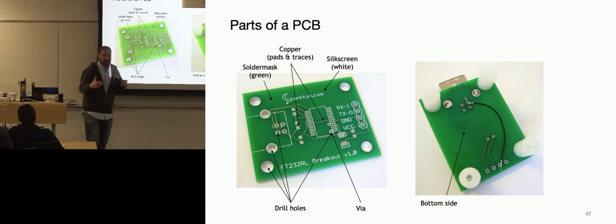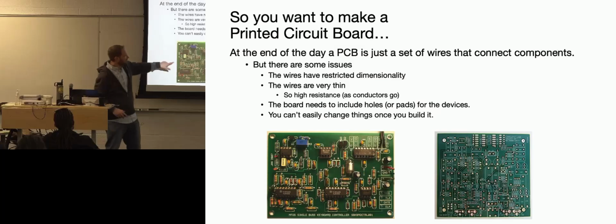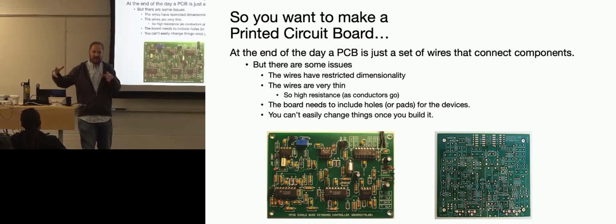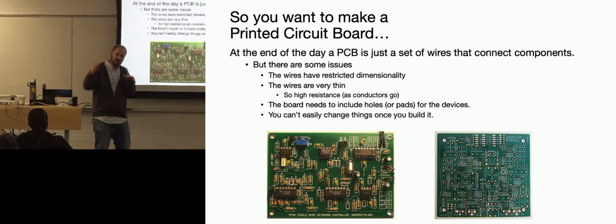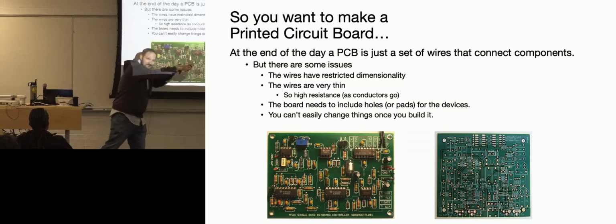One way that they make PCBs is kind of amazing. If you go back to here, like this PCB, they take the whole thing, they put all the parts in here, and then they have what's called wave solder, a tank of liquid solder that's actually flowing over a little waterfall, and they take the PCB with all the parts on it and they just run it through.